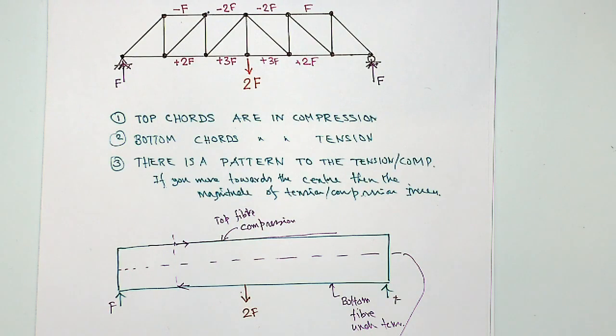When I was doing this particular problem to find the horizontal forces, we just used the equation to make them in equilibrium, but we couldn't solve because both of them are unknown. So then we have to take the moment about a point. So you just consider one side. I also wanted to ask, why is that the case? Because you know the moment is zero at that point. So if there are reaction forces at that point, horizontal and vertical, that would be opposite to the other side. And then you can find out, this is like a simply supported case in that case.